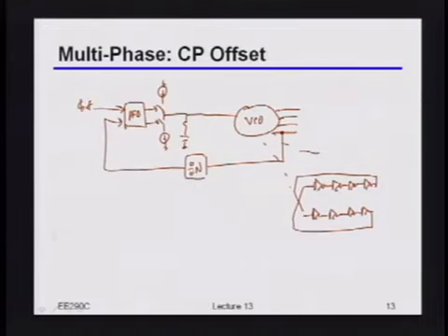Okay? So the basic idea is if I can just hack it so that somehow this phase over here changes, and changes in some controlled way, then actually I can make it so that all of these phases move together, right? Because the feedback is going to force one of these phases to track with whatever sort of offset I introduced. But then all of the rest of them, because I know it's a ring oscillator, are all just directly related to the position at which I put that one nominal phase in the first place, right? So conceptually, does that make sense to people in terms of the trick I'm trying to play?